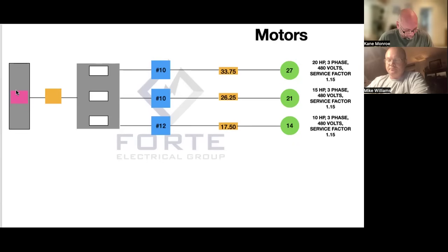That's it. Okay. Step six is kind of easy, but man, you've got to do a whole bunch of other stuff to get to it. But that's it. Just take the highest overcurrent protection plus the FLC of your other motors, and then go to 240.6. I don't remember any questions that were that drawn out. I don't remember a 20-minute question on there. Unless I just totally blew past it and guessed. And sometimes I've done that too.